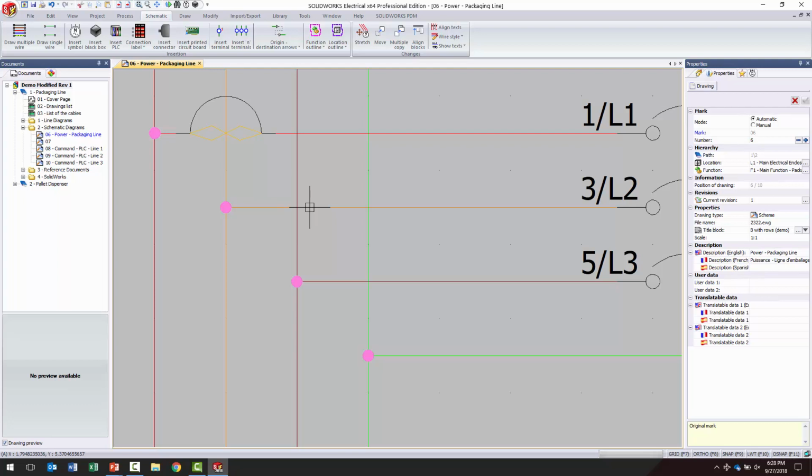We have this case called the wipeout frame, even in this symbol. Now notice it's a black symbol. You could make ones that were each color just so that they matched if you were so inclined. But if you're printing in black and white, it's not going to make a difference. But this yellow frame will still end up printing out as gray. You do have to do one thing. Down in the lower right-hand corner, we have the drawing parameters for this sheet.